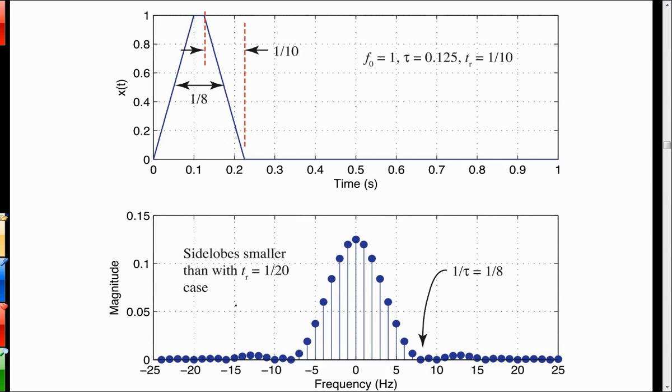You just have more uncertainty if you don't have nice fast edges, because if there's temperature changes or other things, when you cross the threshold, it's not as well defined if it's going over a slope as if it's going steeply up. It bangs over and there's no time uncertainty or minimal time uncertainty. So I don't think people that build Intel Pentiums and things want to have clocks that are too sluggish, because it probably gets into some timing issues with the devices.